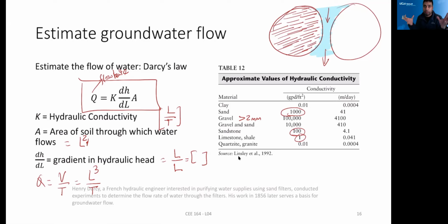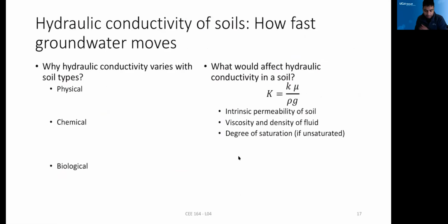In the large sand and gravel, the particles are so big that the capillary effect doesn't exist, because the capillary pressure depends on how close they are together. So that's why if you have a clay material, even though it has high porosity, it has a lot lower hydraulic conductivity. If you take the clay out, once it becomes silt or sand, as the particle size increases, the hydraulic conductivity increases. So this is where I connect together how hydraulic conductivity depends on many factors.